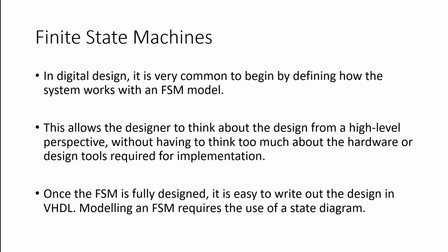And what that means is that when the VHDL code is synthesized into hardware, we do not need to think about how the hardware is implemented. Instead, all we need to do is write the code for this FSM, define these rules that allow us to transition from one state to the next, and when it's synthesized into hardware, it is going to put together the underlying components for that FSM to be realized.